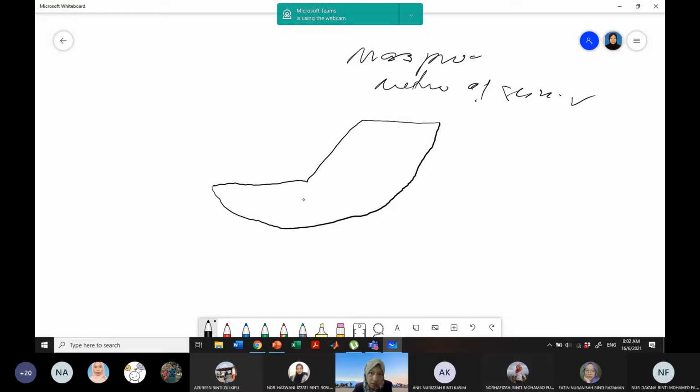So the meaning of the method of slices is that the soil mass above the slip circle will be divided into equal vertical slices. So for this case, let's say we consider the first slice here, assuming as W1. Here is W1, and then we can divide another into two slices as W2 and W3. Actually this is only freehand. What you need to do is divide into equal slices. So this W1, actually we can have another one. Similarly goes to the W3.